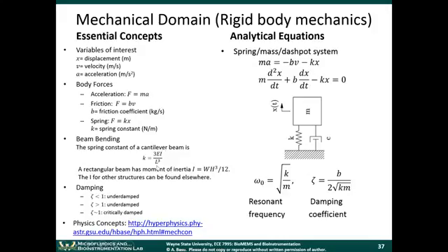And then we have L cubed in the denominator. The shorter the beam is, the higher the spring constant. So another thing that happens at the microscale: if you're scaling down the length, your spring constants will become larger. I'm sorry, if you're scaling down the thickness of the beam along with the length, then your spring constants will remain the same. If you only scale down the length while keeping the other parameters constant, of course your spring constant is going to jump way up. We'll talk more about the scaling of these devices. We'll get to that in a second.